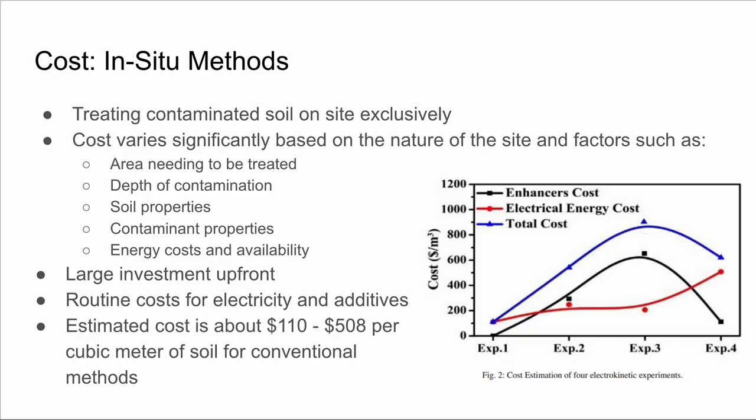And then finally at the end, you also do have a slight remediation cost with this type of remediation, which is unfortunate that you have to remediate after the remediation, but this just ties into the pH gradient that can be created in the soil as a result of this process. So this typically involves digging up the soil directly at the cathodes and anodes, since that's where you have the largest pH disruption. Sometimes you can have loss of vegetation in the area as a result of that pH gradient, so that's just another factor that you need to address as your final closeout of the remediation plan.